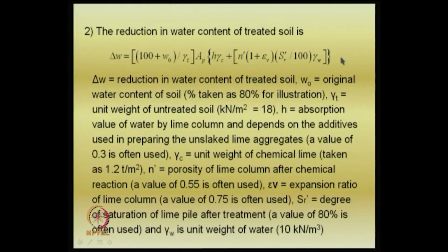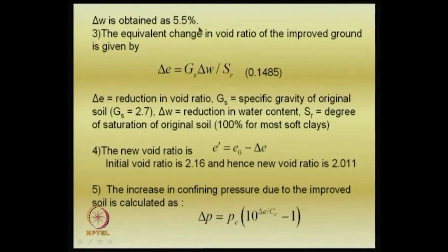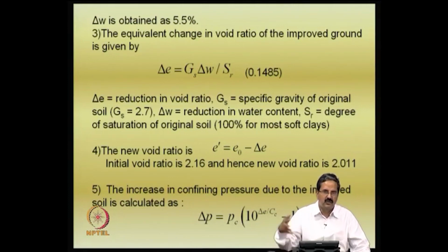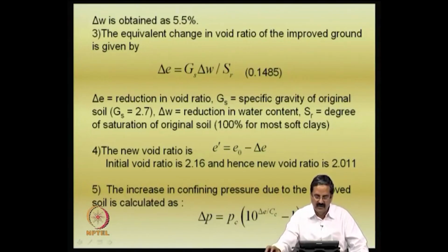So, we put all these numbers here and you get a water content change as something like 5.5%. So, initial water content is about 80%, because of the addition of lime I got it reduced by 5.5%, and it is quite good.